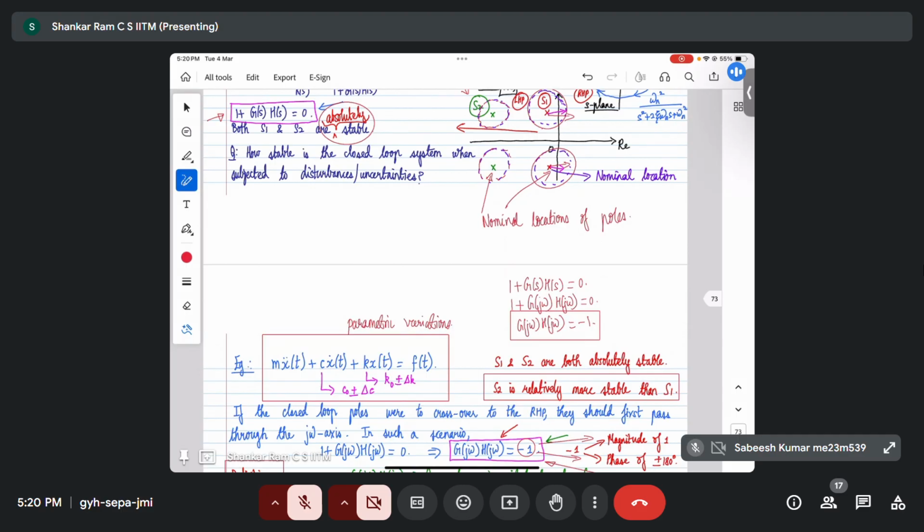So when we have relative stability, we initially have the system stable, with the poles in the left of the complex plane. And when we have perturbations, these poles may migrate to the right of the complex plane. The question that you and I are asking is how tolerant is the system to this? So for that, we once again look at the open loop.